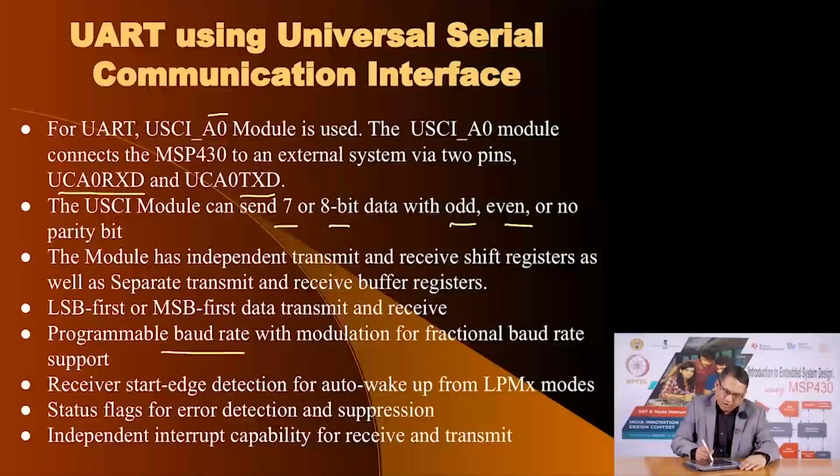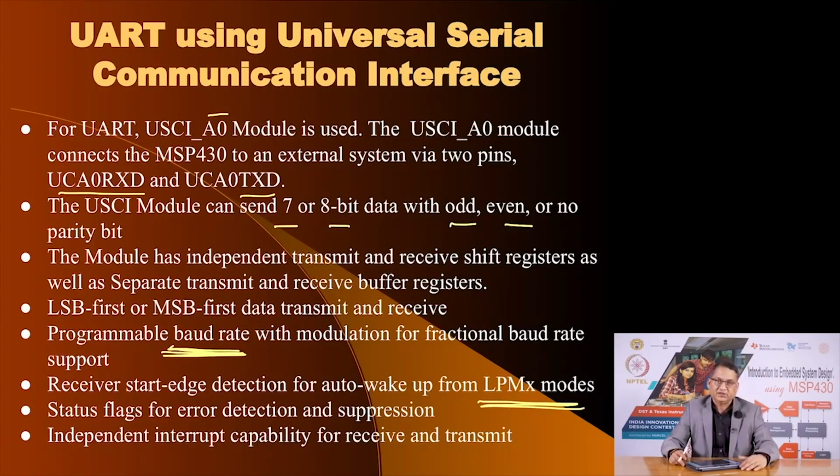You have programmable baud rate, which means you can change it for given clock signals available on your microcontroller. You can change the bit rate to support any of these standard bit rates. There is a mechanism to exit the low power modes once serial communication data is received. There are flags which detect if some error has happened in the communication, and there are independent interrupt capabilities for receiving and transmitting functions of the universal serial communication interface on MSP430.